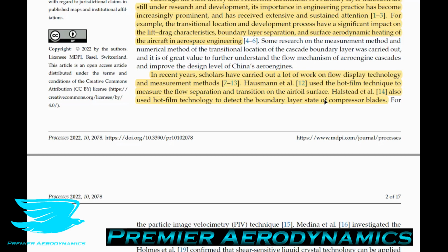However, in recent times, there have been a lot of advances in terms of hot wire and hot film technologies. So the differences between them aren't that great. For example, Dantec, they make hot wires which are very thick now, and that means that they're much stronger. So that advantage that hot films once had is no longer there. With these hot wires, though, their frequency responses dropped, but their strength is there. So as I mentioned, the differences between them are kind of becoming blurred as we progress.